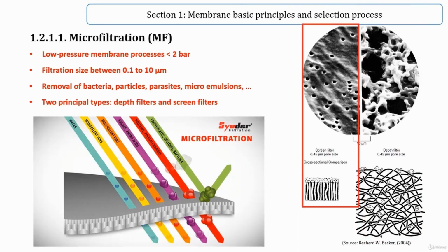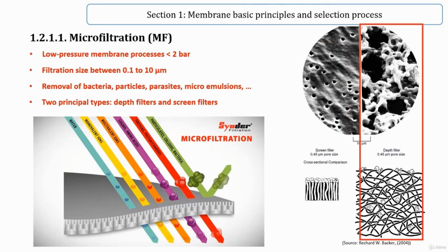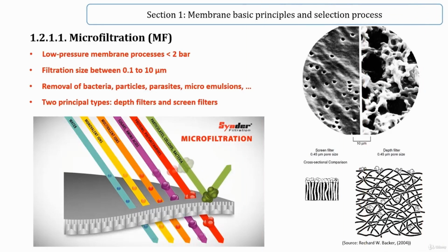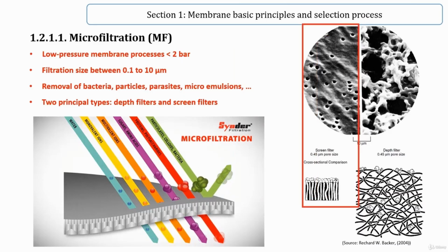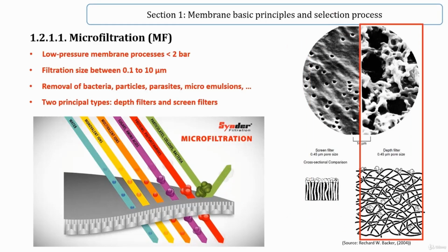Screen filter membranes rapidly become plagued by the accumulation of retained particles at the top surface. Depth filters have a much larger surface area available for the collection of the particles, providing a larger holding capacity before fouling. Screen membrane filters are preferred for cross-flow microfiltration systems, but depth filters are usually preferred for dead-end operating mode.